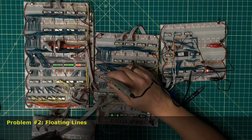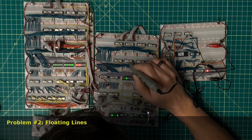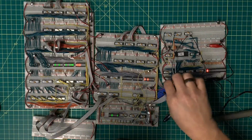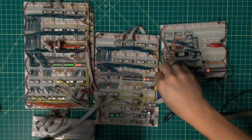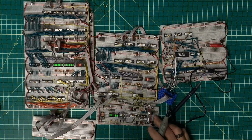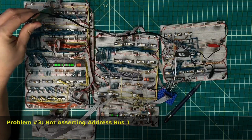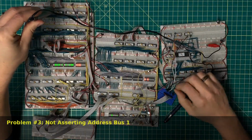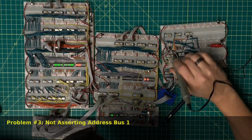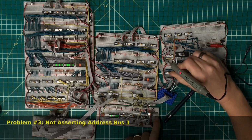Something upstream is causing it to go high. Let's see here. That would be this. Okay, I got multiple paths of power there now. So now the next question is, am I asserting? That's high, that is not asserting, and it should be asserting. So do I have this incorrectly? So that's low, that's low. Is my clock working? Clock is working.